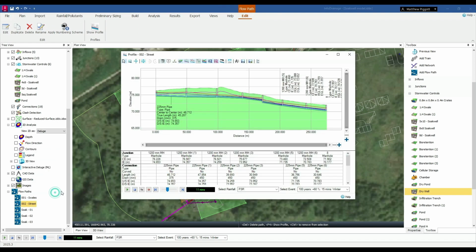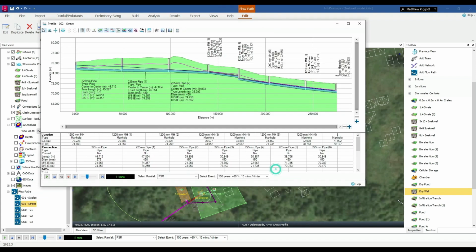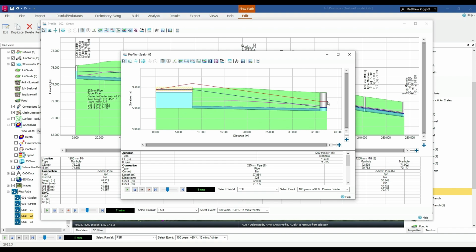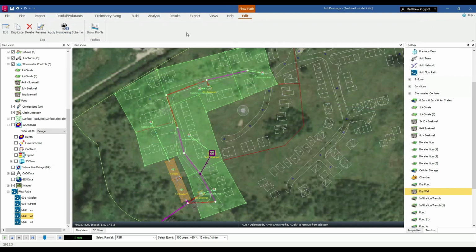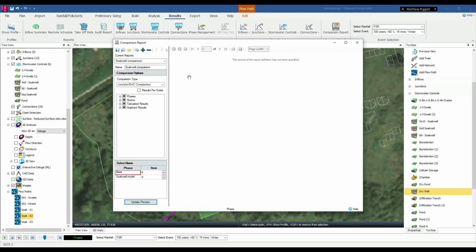If I go to the soakwell scenario and look at that same profile, we can see with the maximum HGL, it's not reaching any freeboard. So we're actually attenuating those flows with our soakwells in this design. You can see here the level in the soakwell. It looks like it was hitting the freeboard, so maybe we can increase that volume if need be.